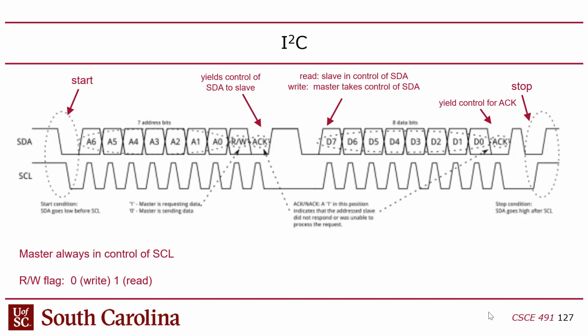And then the acknowledgement. After I send the read-write, I toggle, toggle, set read-write, toggle, toggle. Then I sit back and I wait. Well, actually, I don't wait. I toggle the clock again, toggle, toggle. And then when it's high, I'm reading the acknowledgement from the slave, right?